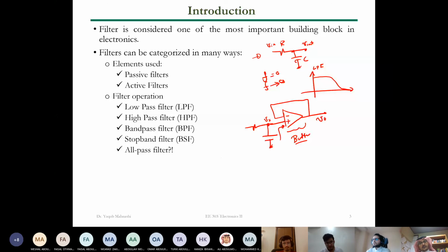So there is no gain in the passive element. I mean using the capacitors. Of course, someone might say, what about the inductor? This is a different story, but let's focus on the capacitor here. And even with the inductor, you cannot get more than V input unless you have a diode or other switching element. But for now, let's focus on the RC filters. So we don't have gain here.